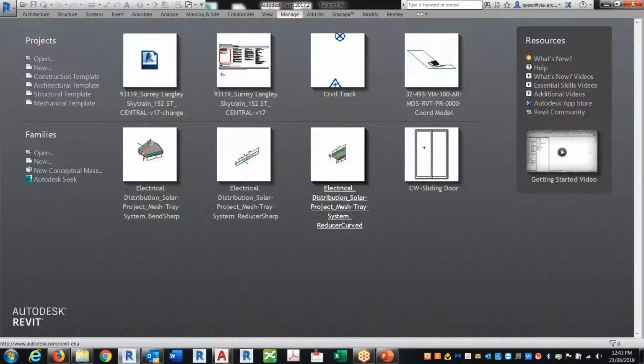So you don't have to physically change the building itself. You don't have to take the building and rotate the whole thing. No, don't do that. That's a mistake. I've seen people do that. It's a mistake, don't do that. Always rotate the CAD based on where you want to position it, and then just acquire coordinates, and then you're set. Okay, so this one I kind of figured out in a couple of days.